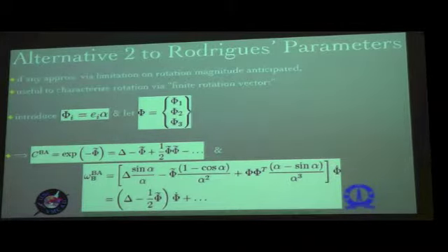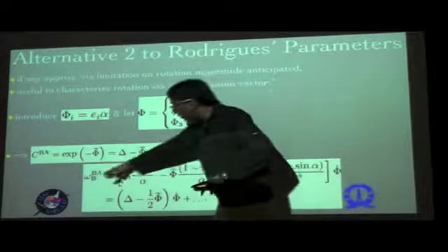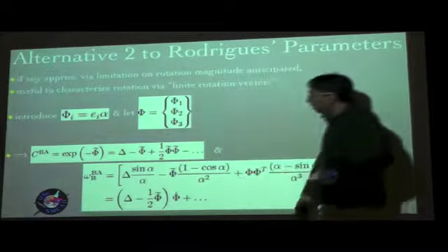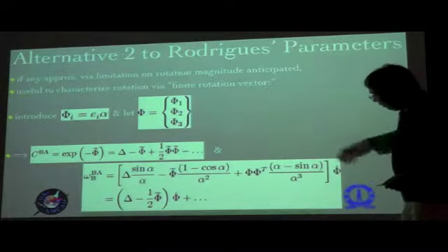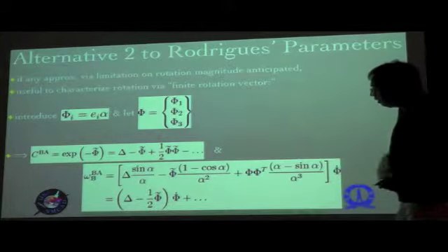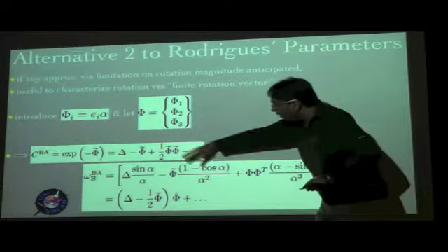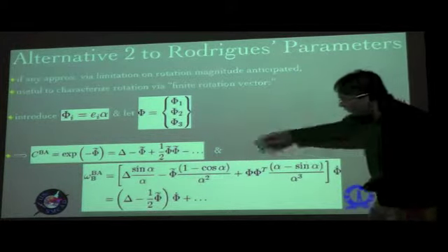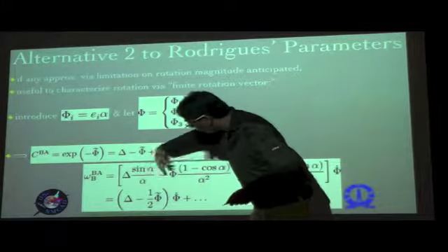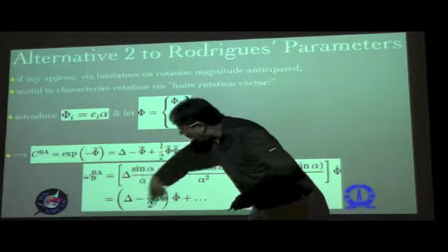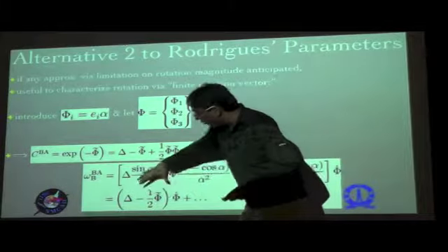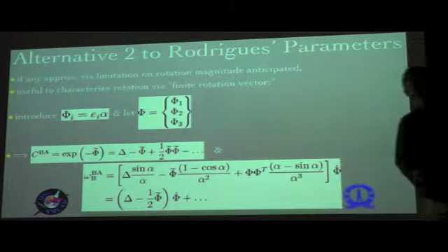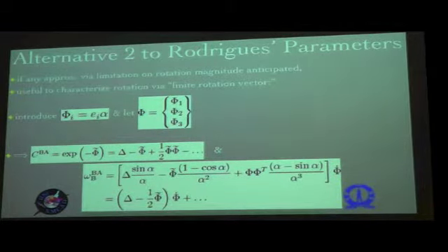So this is the expression you have for the angular velocity expressed as a column matrix in the big B basis, and then you again have terms involving the phi dots and the alphas as well, and typically the first few terms of this are utilized in determining it, and of course it can be expressed in a simpler fashion. So this is, for example, what you would take in many situations, especially when you're dealing with local rotations. We will see one of the applications would be to use this formula for omega and CBA.